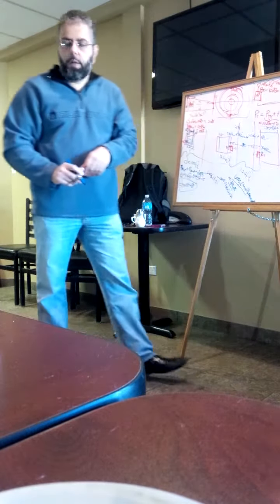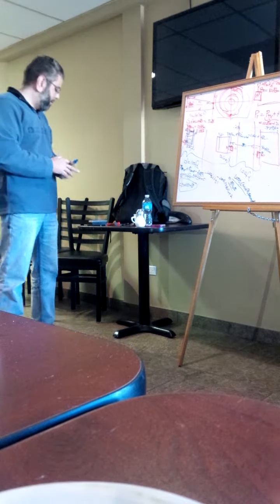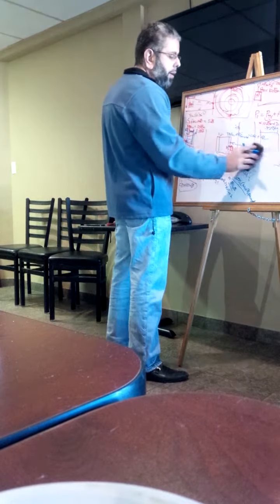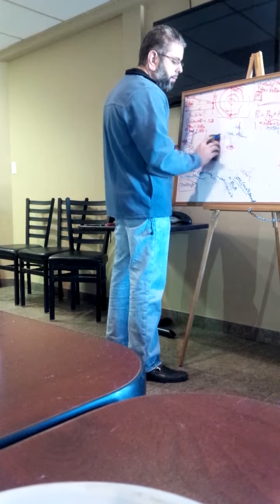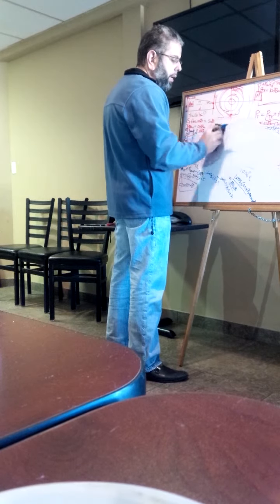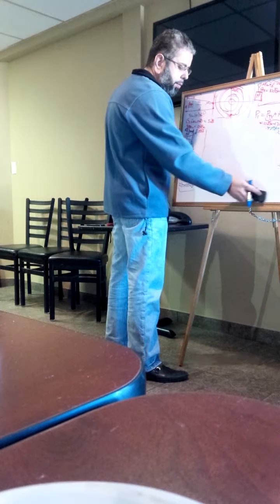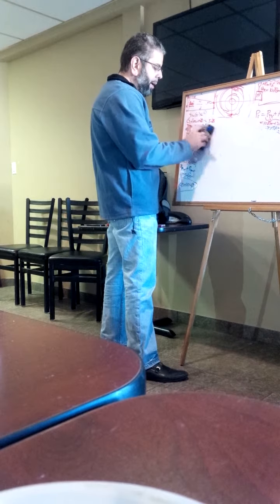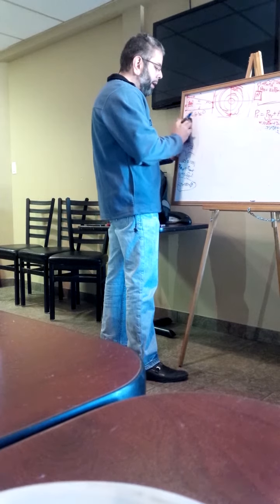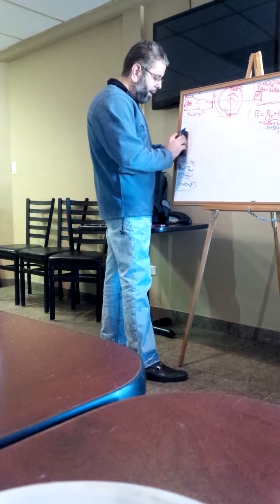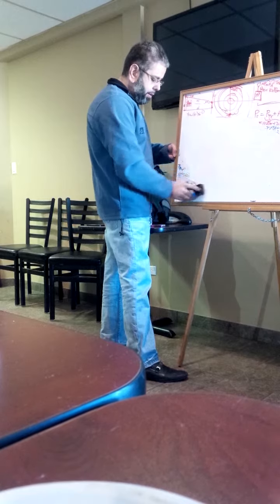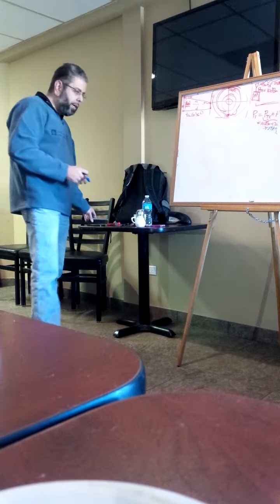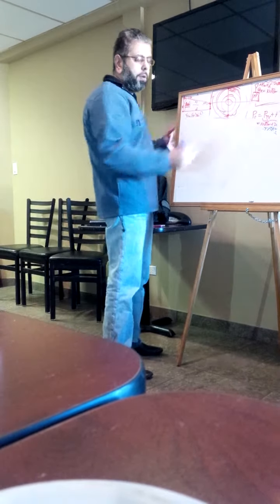RX performance. What I want to focus on with the RX performance is, let's say someone tells you that you have received a minus 70 dBm signal. What does that mean for how good my performance should be? Should I be able to do 50 megabits per second with minus 70? What's my MCS, my modulation and coding scheme, that I'm capable of performing at with minus 70 dBm? It's not enough information just to determine, but it's a start to say if I was at minus 70, what would my performance be?